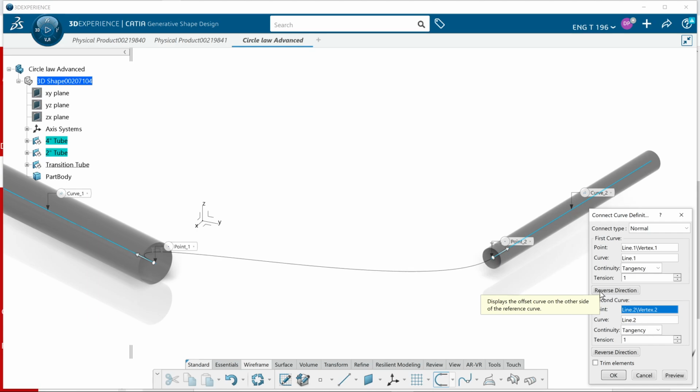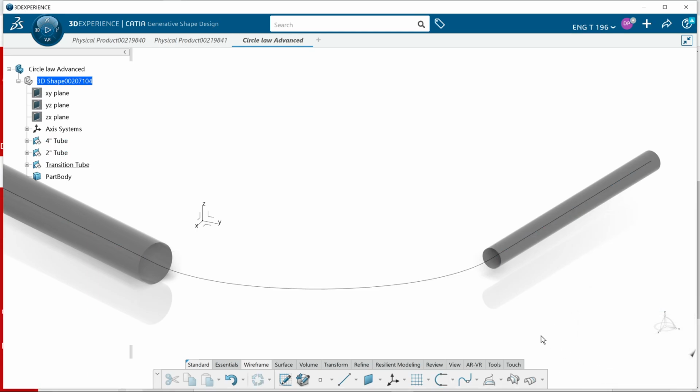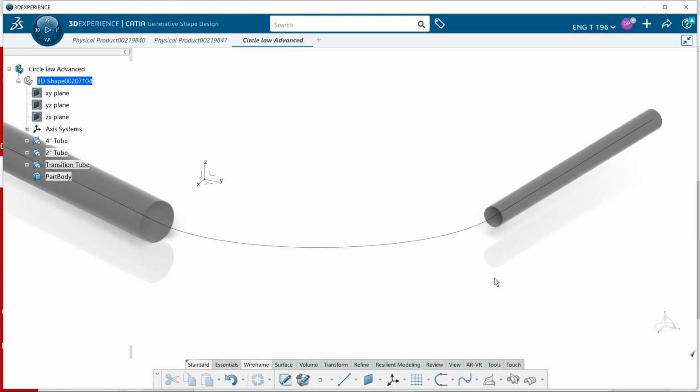Now, it shouldn't be a big deal. I'm going to hit invert. That should fix it. So when I go into production, or you take the 196 class and I talk about electrical runs or tubing and stuff like that, hydraulic runs, I join this line, this curve, and this line together, and it's called a logical line. Even though it's a curve, they call it the logical line. Whatever's the center of your tube defines itself as a logical line.